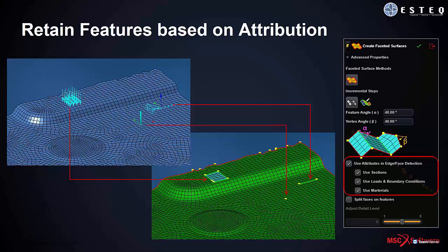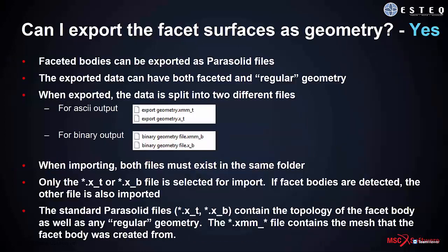So you will automatically see if a patch was loaded with a pressure, Apex will create a section or a portion which basically becomes a separate surface. If there was a point load, a mesh seed point will be created in the geometry as well as any line features. So those points of application essentially become features in the geometry that you can use further.